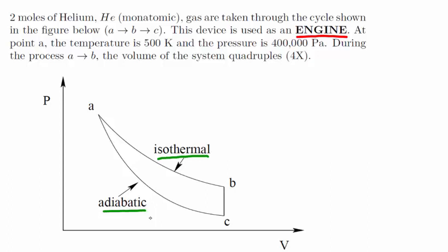The adiabatic process is the one in which heat does not flow, and the isothermal process is the one in which temperature does not change. However, these are not the same process. When heat does not flow, the temperature does change because internal energy is converted directly to work. When the temperature does not change, the heat certainly does flow because in this case, the heat is converted to work.